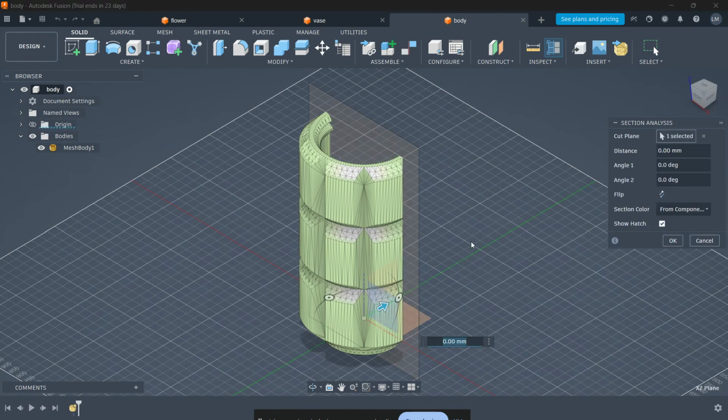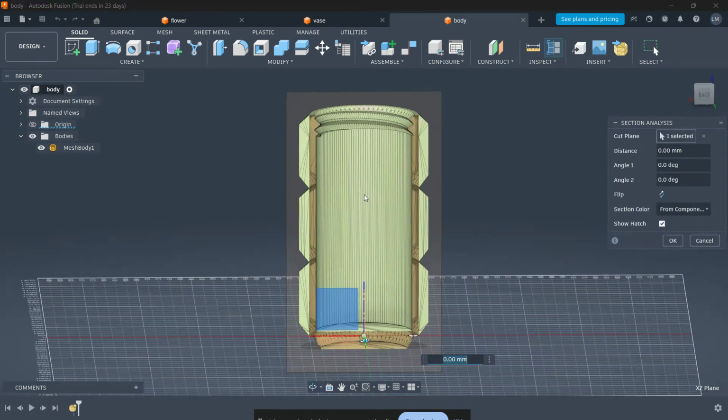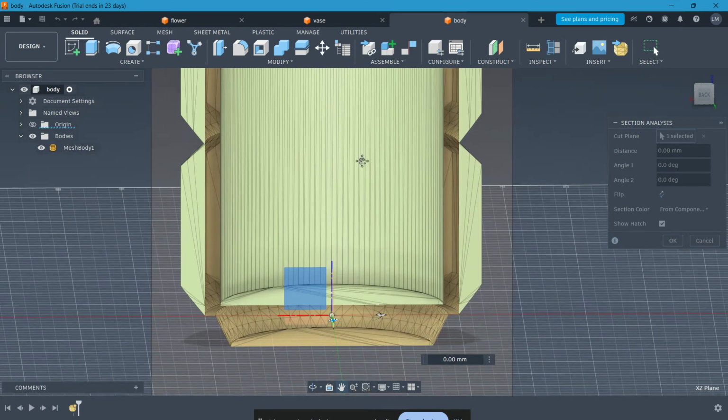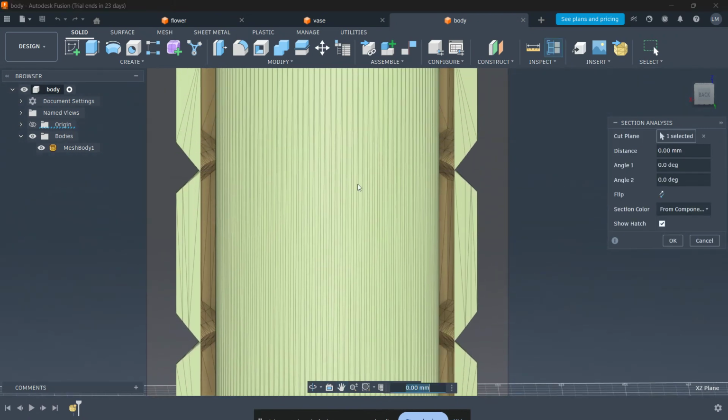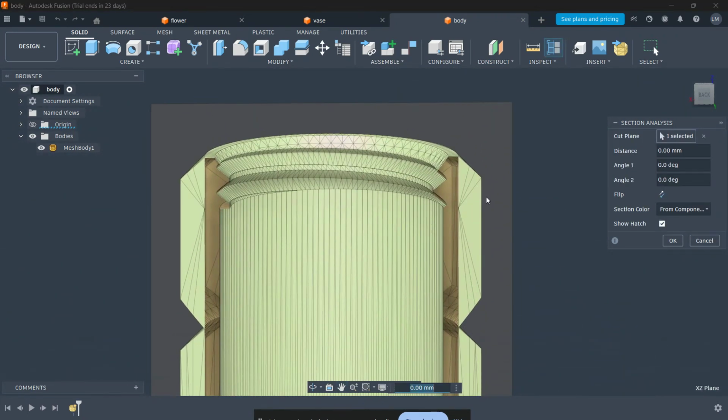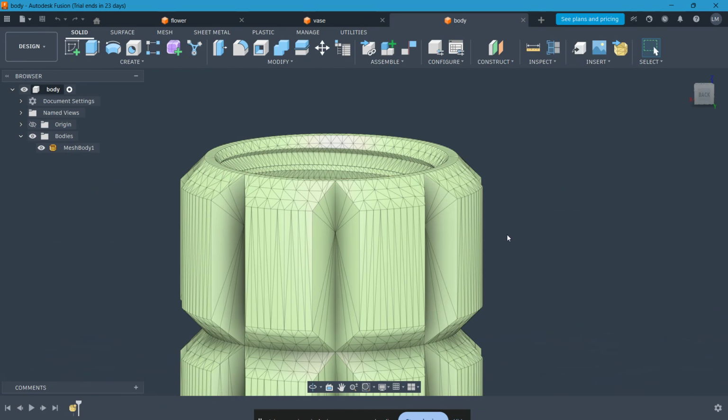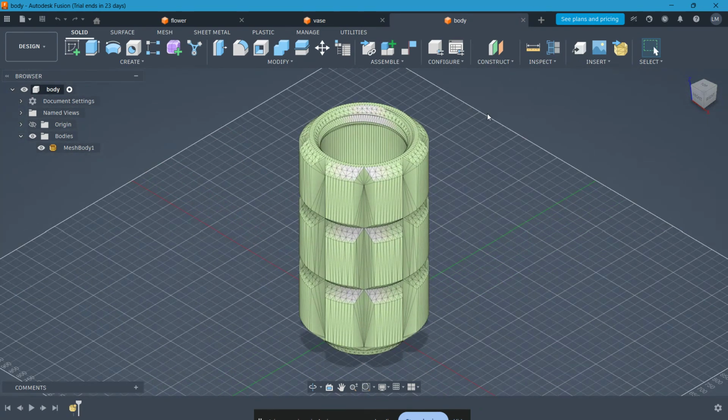If you're working with imported files like STEP or STL, this is a very common source of errors. Imported geometry often comes with hidden defects. In this case, use the repair workspace or try converting the mesh into a solid and rebuilding problem areas. Sometimes the best fix is to recreate certain features from scratch instead of relying on the imported geometry.